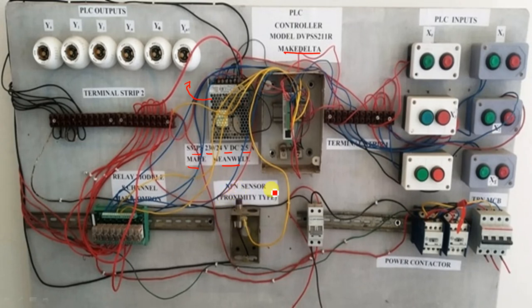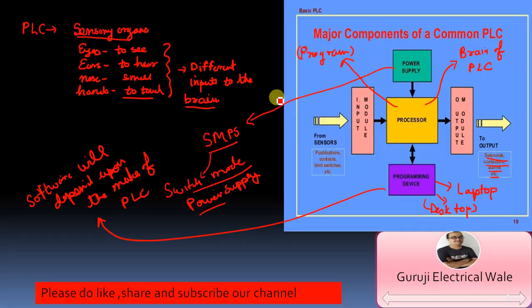Okay, so here are the different sensors which we have used. An NPN type proximity sensor is there. These are the push buttons, as I told you earlier, which are basically providing inputs to the input module. So this is the input module of the PLC, and this part here is the output module. The input module is used for connecting all the different sensors to the PLC, as you can see here. Clear?